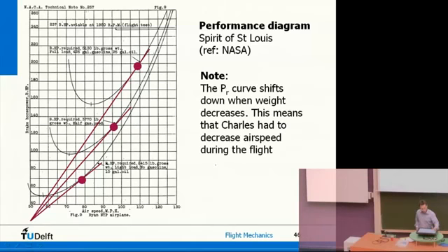So this is one of these power curves, and the point, if you draw a line from the origin over there, that's the minimum drag condition. So this guy, he couldn't look outside, so all he was doing was calculations on board to figure out how fast you actually have to fly to be in the minimum drag condition. So he was doing constantly these calculations. Flight took in the order of 30 hours, I think.